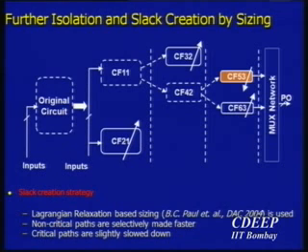The interesting thing is that by looking at the number of literals in each of those cases, I have a fair idea of what the longest path is. In some cases, some paths are going to be similar, but that's okay. I know which are the longest paths and which are the shorter paths. Now, on top of that, I can do something. I can do sizing. So what kind of sizing can I do?